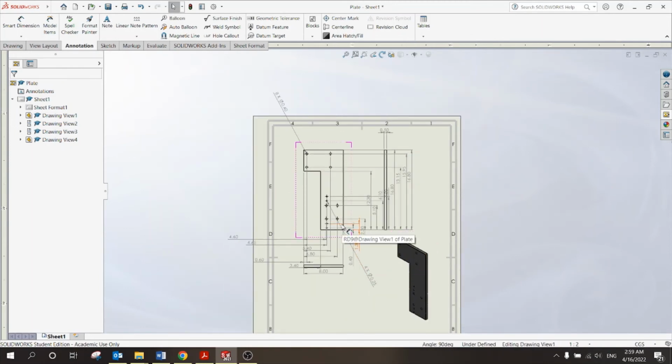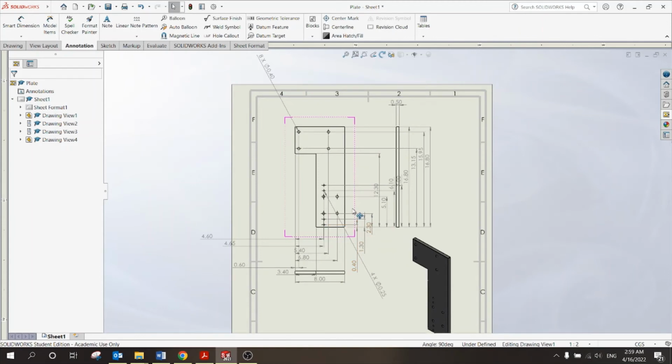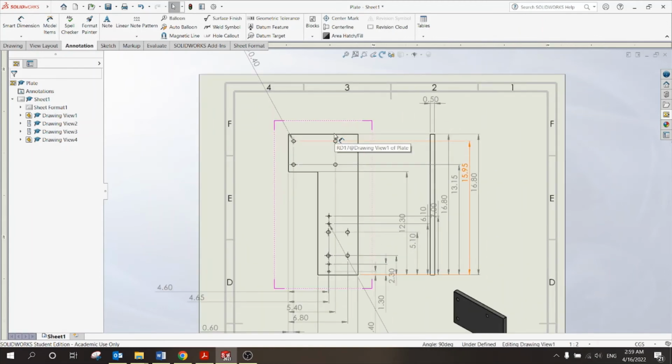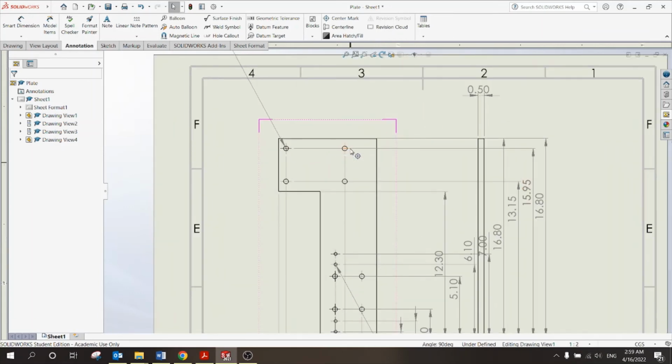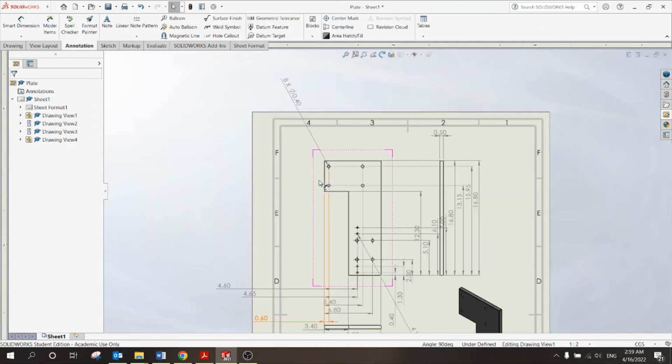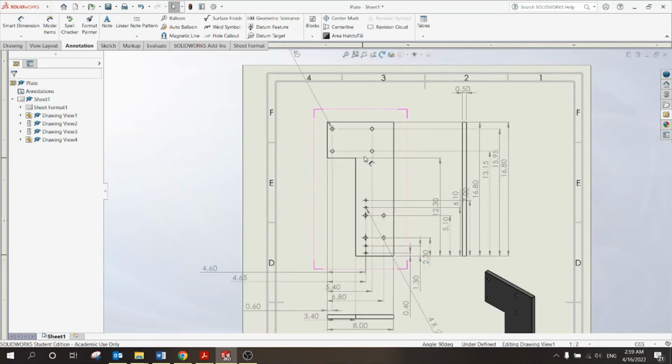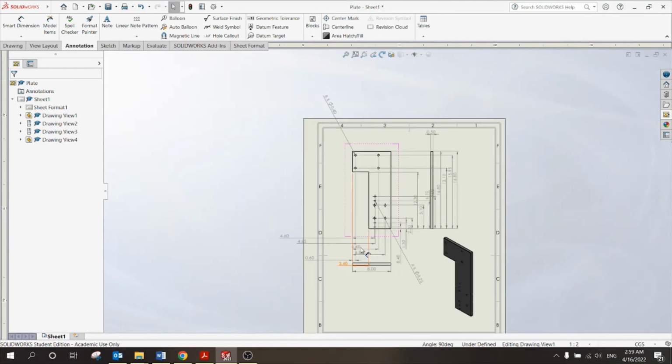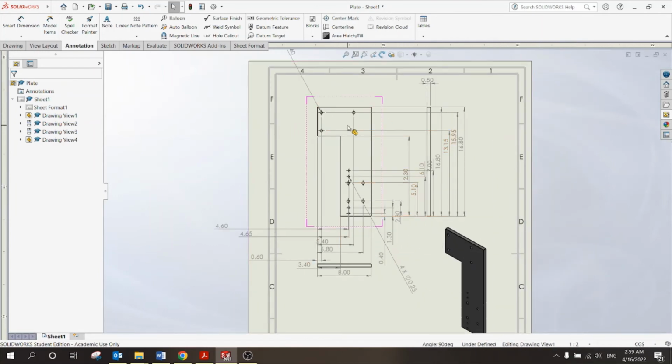But the issue is, for complicated parts, or like this part, it has many dimensions, because each center, for example, needs the radius of the circle, the X components and Y components, and I have 4 holes, and I have 16 holes, and I have different parameters. So in this case, auto dimension will not work. But for simple drawings, I can easily use auto dimension, and I can delete any one of them based on what I need to show to the manufacturing team.